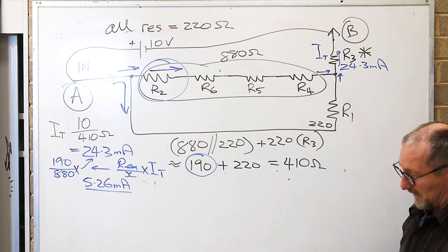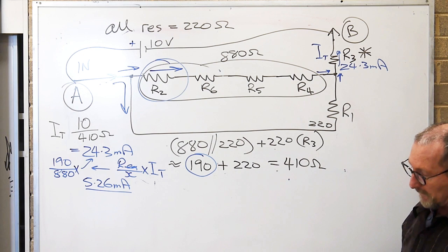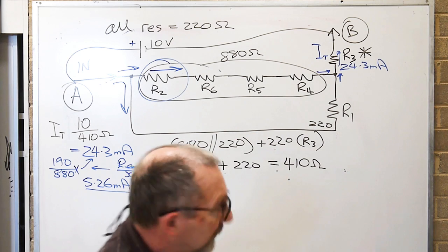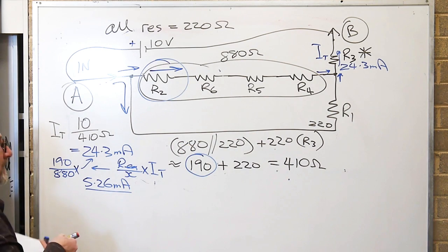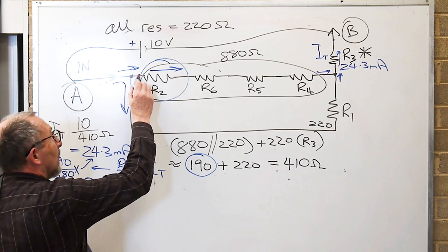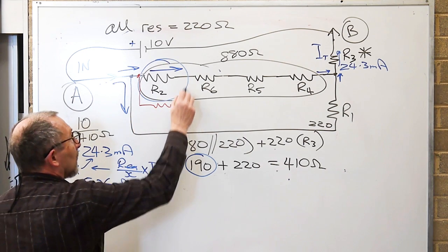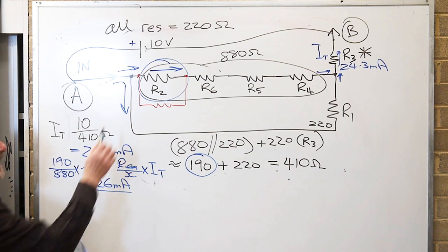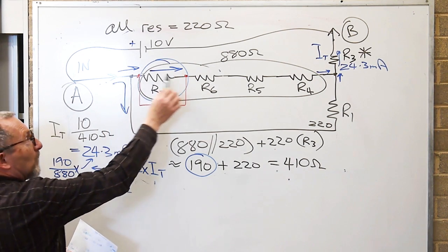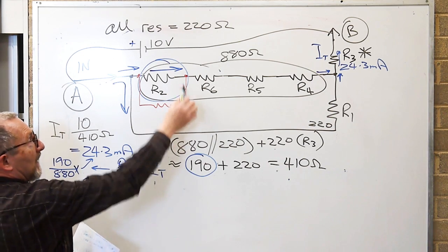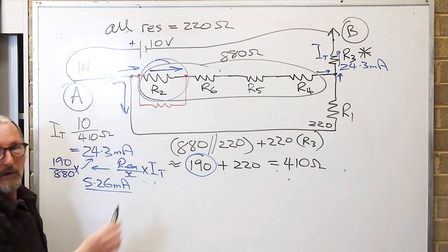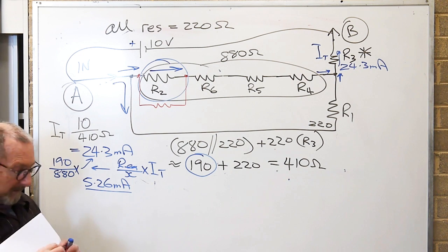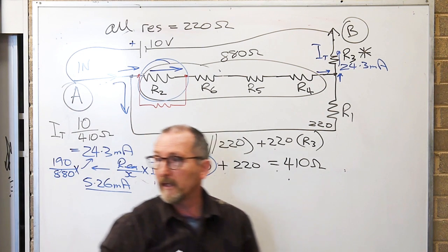R2 and R1 in parallel. No, if R1 and R2 were in parallel, they would have had to, on the breadboard, have actually ended up like that. And if you look at R2 on your breadboard layout in the question, and you just take one end of that resistor, see if you can locate R1 pin for pin sitting across it, and you can't. So it's definitely not in parallel with it. Any other questions?